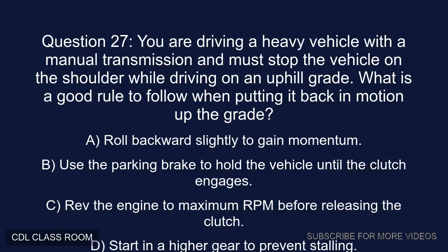Question 27. You are driving a heavy vehicle with a manual transmission and must stop the vehicle on the shoulder while driving on an uphill grade. What is a good rule to follow when putting it back in motion up the grade? A. Roll backwards slightly to gain momentum. B. Use the parking brake to hold the vehicle until the clutch engages. C. Rev the engine to maximum RPM before releasing the clutch. D. Start in a higher gear to prevent stalling. Correct answer, B. Use the parking brake to hold the vehicle until the clutch engages.